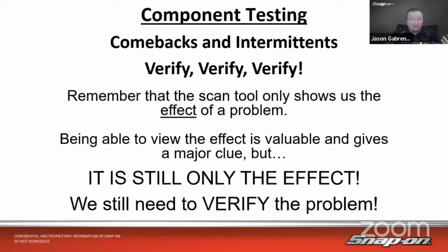I think back to my days in Subaru. I remember one time I had a car come in with a P0340 something. I think it was a cam sensor code, regardless. I don't remember the exact number, but it was a cam sensor code. And if you look through every line on that flow chart, not once does it ever say to test that sensor, look at the sensor, or replace the sensor. So you mean to tell me that I'm getting a code for a cam sensor and nothing could possibly be wrong with that sensor, because I'm not actually testing the sensor? All right. So I learned real quick: don't trust the flow chart all the time. Test the part. It's always best to go direct to the part and test it and verify.